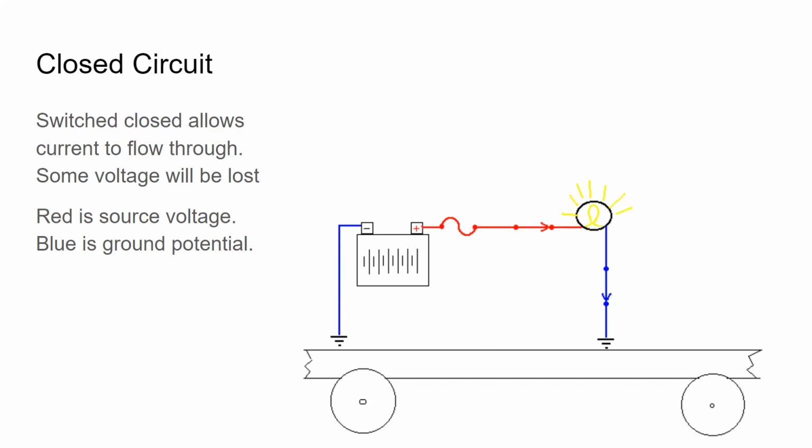But what I'm trying to illustrate here is if you have a voltmeter and you put your black probe there, and then you take your red probe, it really doesn't matter if you put your red probe there, or there, or there, it doesn't matter. If you go here and here on the battery, you should have about 12 volts. We'll call it 12 volts for the sake of keeping it simple.